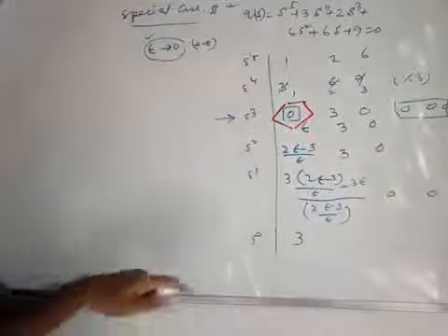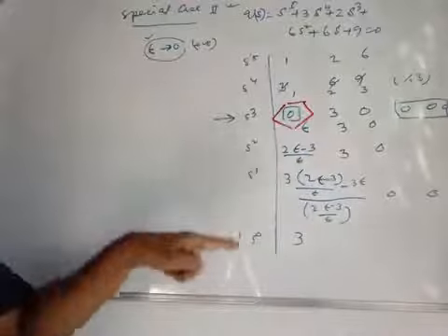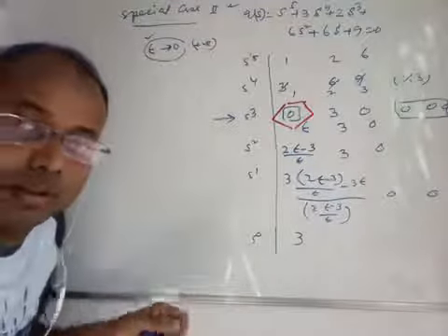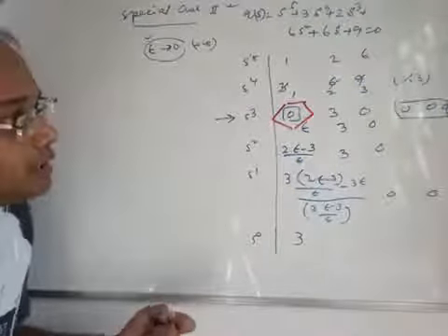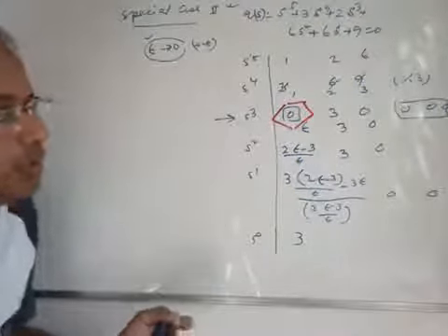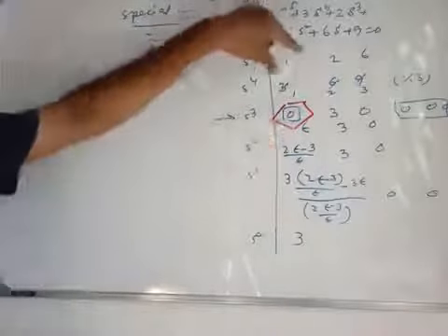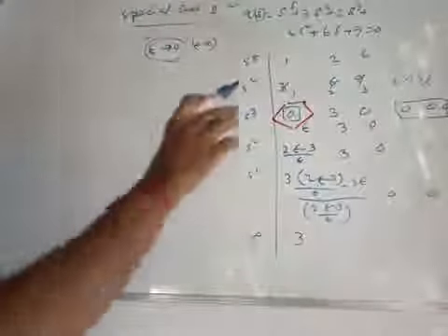So the Routh array can be formed with the help of a small quantity epsilon which tends to 0, considered very close to 0 but not equal to 0, and this is a positive quantity, right? So if this is a positive quantity, see what you are getting in the first column of the Routh array after considering this epsilon.